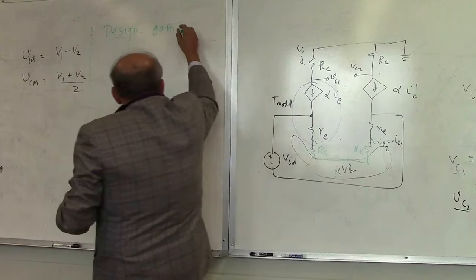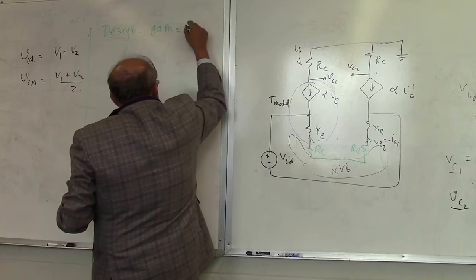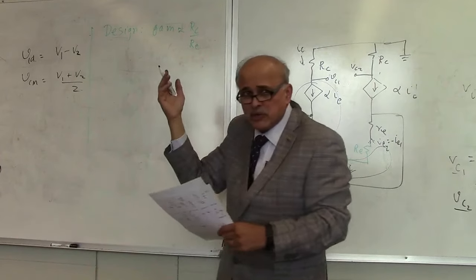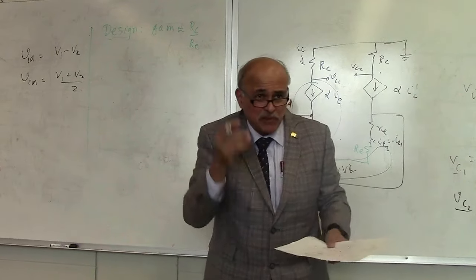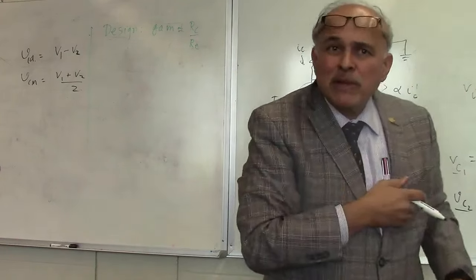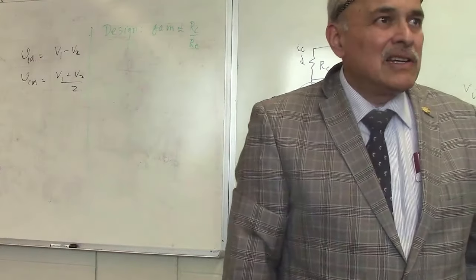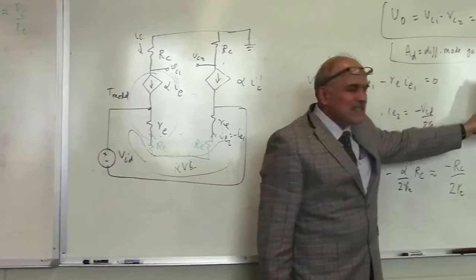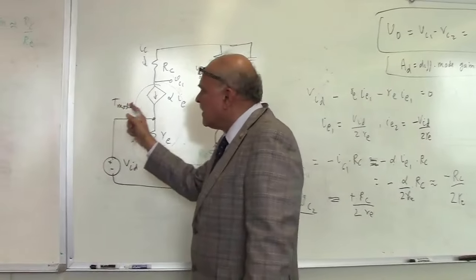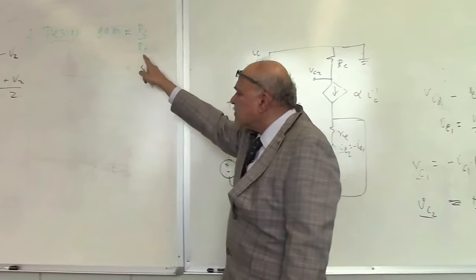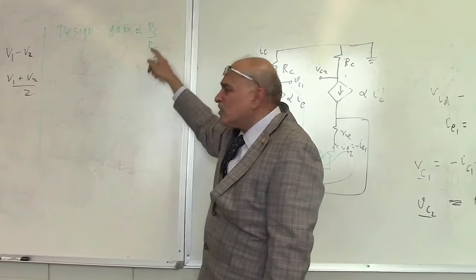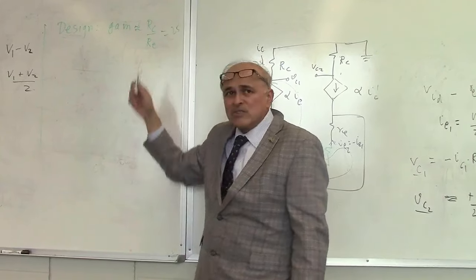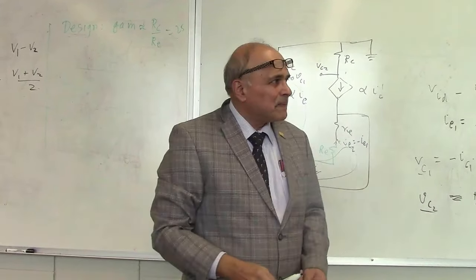So you want this approximately RC over RE. If you ignore the small re, you can add 25 millivolts to it if you want at room temperature, but we don't even know what the room temperature is in this room. So we just have to guess it. So we don't really know what our re is going to be, but we want to minimize the effect of the variation of re, so we'll just use the external gain. So we want this to be equal to 25 to 27, something in that range. That allows us to choose the ratio of RC over RE. All right?